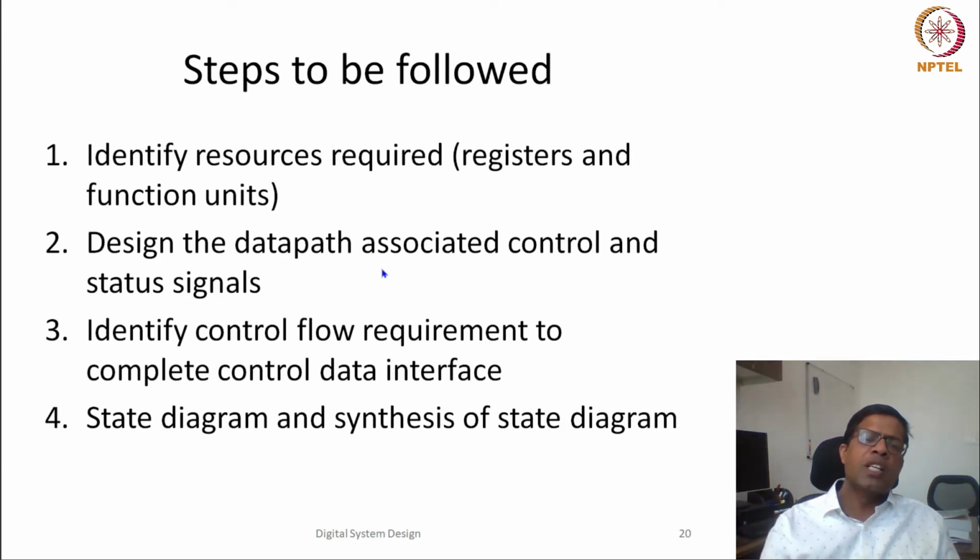Along with that, we will also identify which operations would be done in which particular clock cycle. That sequencing of operations would help us in drawing the state diagram, and then that state diagram could be synthesized. We can determine how many flip-flops they may require, write the next state equations, and then we can also find the combinational units which are required there.